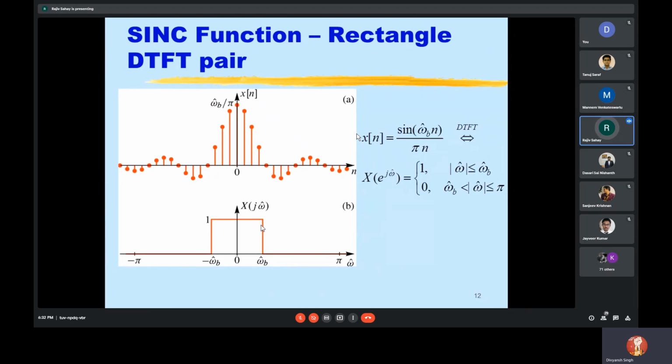And that impulse response will have finite terms on the negative axis, and therefore it will be non-realizable. So it is a non-causal system. So if you have an ideal low-pass filter, it is a non-causal system and it is non-realizable.